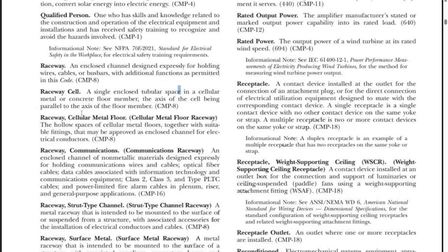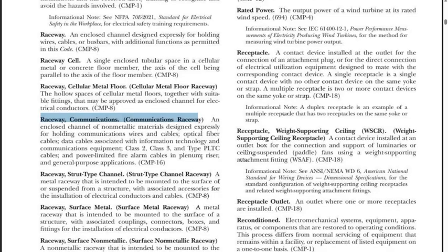All right, now they do have a few extra ones here. We're not going to really get into those, but you can see there are communication raceways, for example, things for like fiber optics or data communications for the internet, for any kind of data communication system, satellite systems, fire alarms. There's all kinds of things that can be considered a raceway. In fact, here in the communications raceway, there is an odd one, which is this right here, that word. Fire alarm cables in plenum.